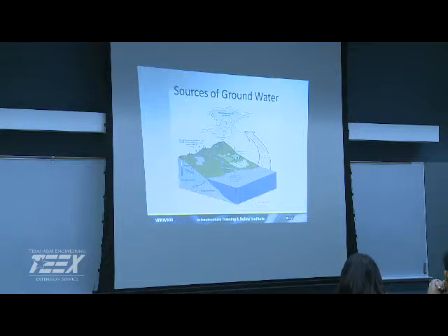And then one of the big things we were talking about earlier is our saline groundwater. There are a lot of brackish water aquifers. In Texas, they're working on maps right now for them. That's the next wave of water, the next water source. It's a lot less in total dissolved solids than if you were pulling it off of the Gulf of Mexico. So it's a lot easier to treat, about 10 to 100 times less depending on your source.